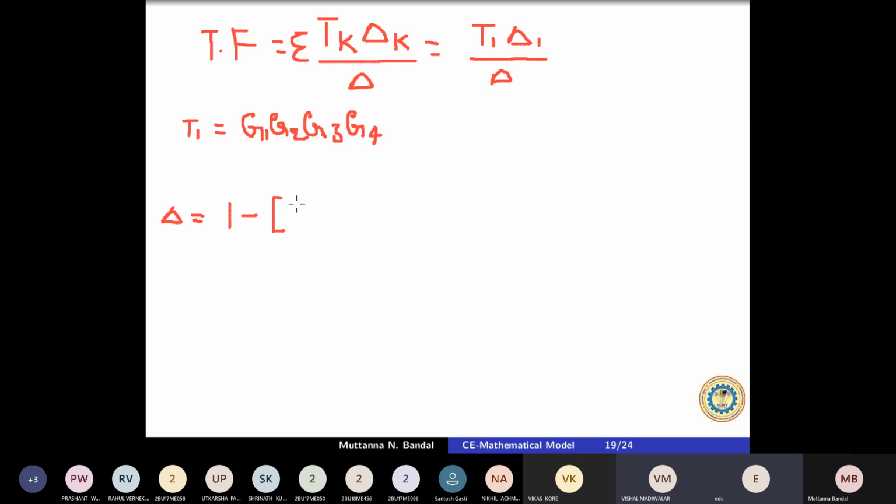Three. So those were L1 plus L2 plus L3, and plus the two non-touching loops. Are there any in my signal flow graph? No. So this term becomes 0. And I also don't have three non-touching loops, so this is also 0.